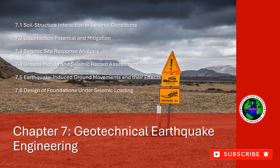Soil improvement techniques such as vibrocompaction, grouting, and dynamic compaction to increase the density and resistance of soils to liquefaction. 4. Seismic settlement and differential settlement. Seismic settlement occurs when loose or soft soils undergo compression during ground shaking.